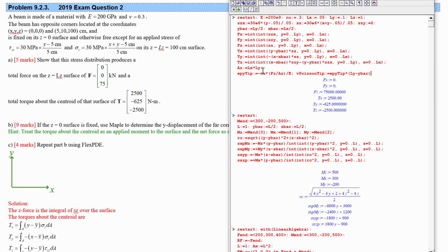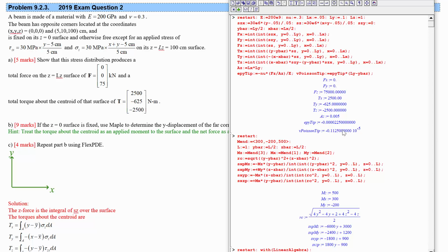So if we take that strain that we worked out and we multiply it by the length, we'll have the change in position. The distance, so we multiplied it by the distance from where it's going to hold still. All right, how much does that move? Not very much, about 1 micron.